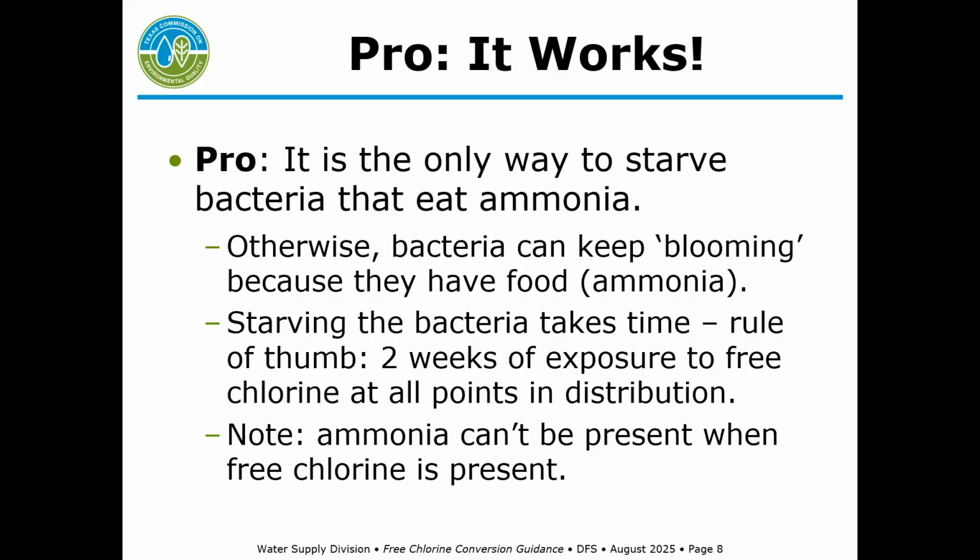So what are some pros of doing a free chlorine conversion? It's the only way to starve the bacteria. Otherwise, the bacteria can keep blooming or growing because they have food, ammonia. It's also important to realize that starving bacteria takes some time. Just a rule of thumb that we encourage PWSs to use is, give all points in your distribution system at least 2 weeks of exposure to free chlorine in order to have it successful. So that means 2 weeks at the farthest part of your distribution system as well.